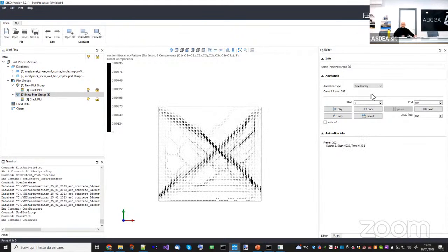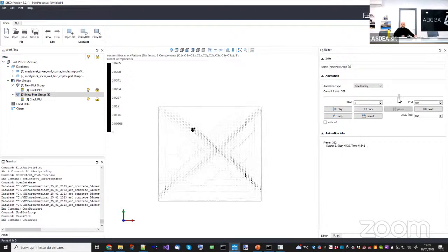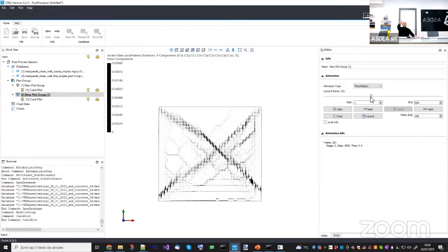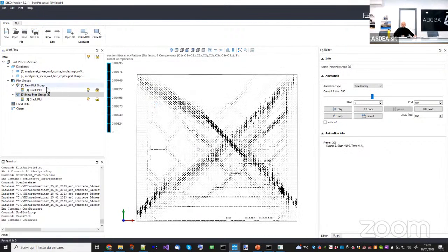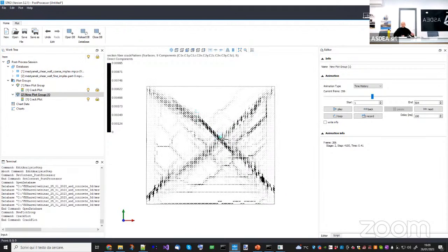Okay, so when you're up to here, you can see the amount of cracks, except from this point now, because the wall is completely broken in those points, but typically here, the crack has the same size as the other model, okay? So 0.01, 1 centimeter more or less. Why? Because the crack opening is a physical quantity, okay? But the strain associated to this crack opening changes with the mesh. So imagine you have a crack, which is a 1 centimeter crack, okay?